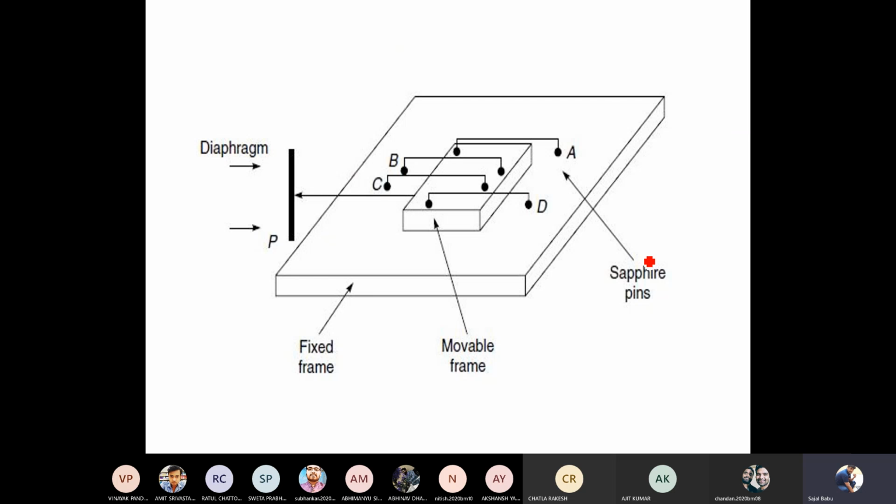That means here the length or change in displacement of the wire. What that means is the length of the wire. Okay, whenever you apply pressure on the wire, the wire will get elongated, and whenever you remove it, the wire will get compressed. So the basic function of the strain gauge is to convert the pressure into voltage, and that is acquired by using a resistor. Okay, because the length of the resistor is going to vary here. Okay, so this is one type of strain gauge here. So we can call this an unbonded strain gauge.